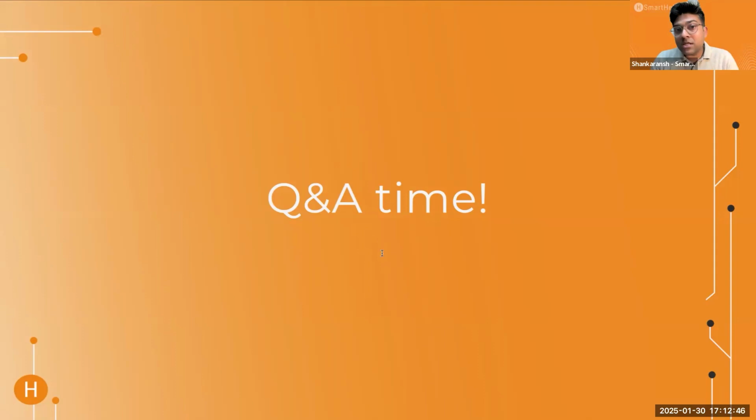Not everything is going to work. There are certain things, for example, module degradation, that naturally, because of the nature of the fault, will take a longer period. But that's also the beauty of the solution: since it is based on physics, I don't need a large amount of data to train my models. So even if the plant is 1 day old, and if there is a resistive fault or an MPPT issue, I can detect it right away.